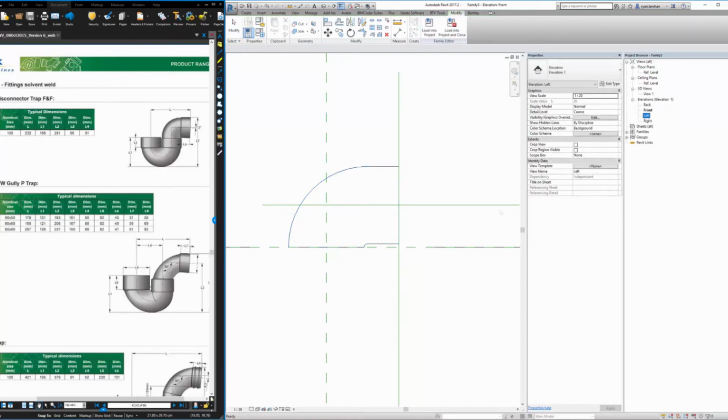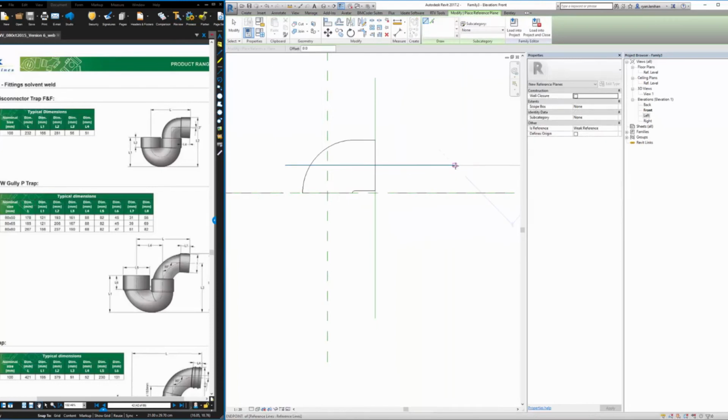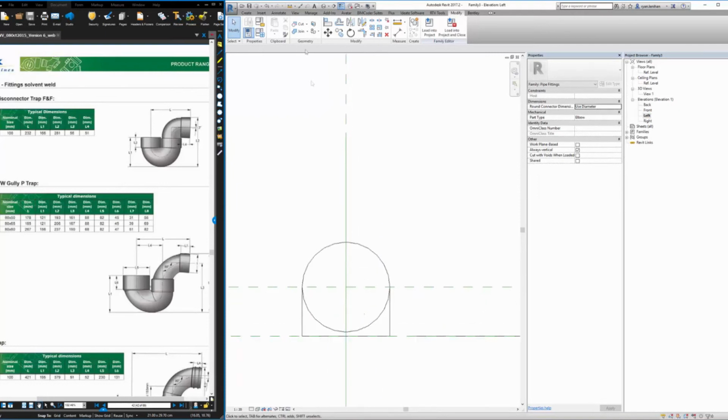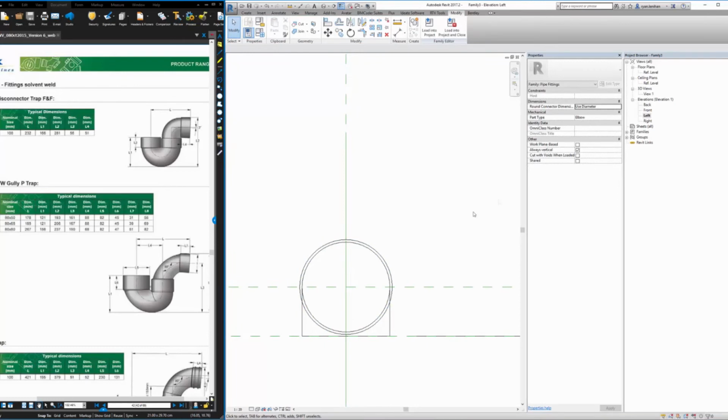So, of course, as always, no one likes an angry hydraulic designer. Actually, nobody likes hydraulic designers. That's probably true as well. Nobody likes an angry hydraulics designer, so we better put that socket on. So we've got our reference plane there. And again, it's a circle, a line and lock, 55 mil plus 3 mil for the wall thickness, total of 58, and that's our socket.